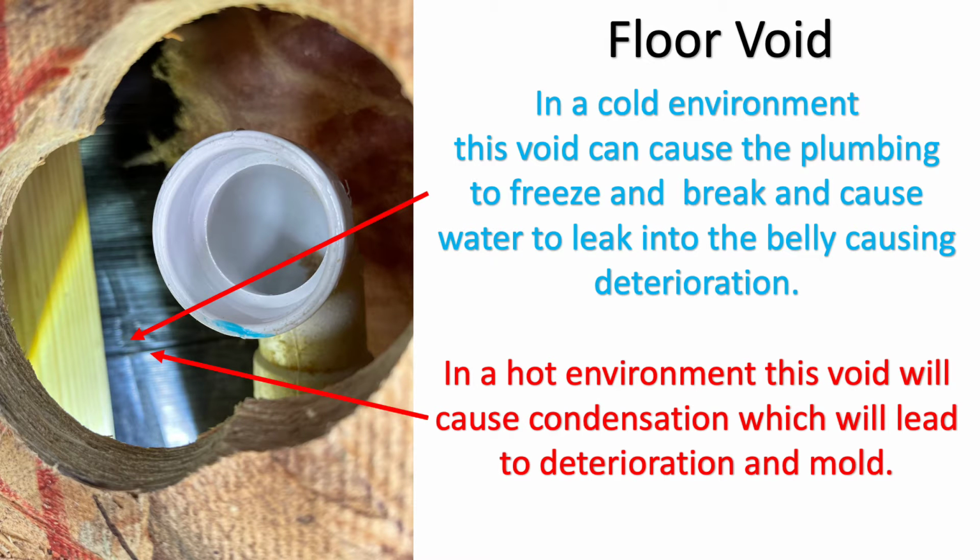Floor void. In a cold environment, this void can cause the plumbing to freeze and break and cause water to leak into the belly, causing deterioration. In a hot environment, this void will cause condensation, which will lead to deterioration and mold.